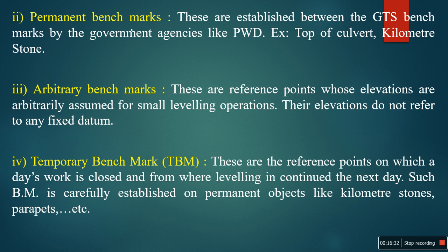Then last, temporary benchmark. These are the reference points at which a day's work is closed, or from where leveling is continued the next day. Such a benchmark is carefully established on permanent objects like kilometer stones, parapets, etc. Suppose you are conducting surveying with leveling. At the end of the day's work, near the end point, you have to consider a permanent stone for the continuation of the next day's work. So that reference point is called a temporary benchmark.